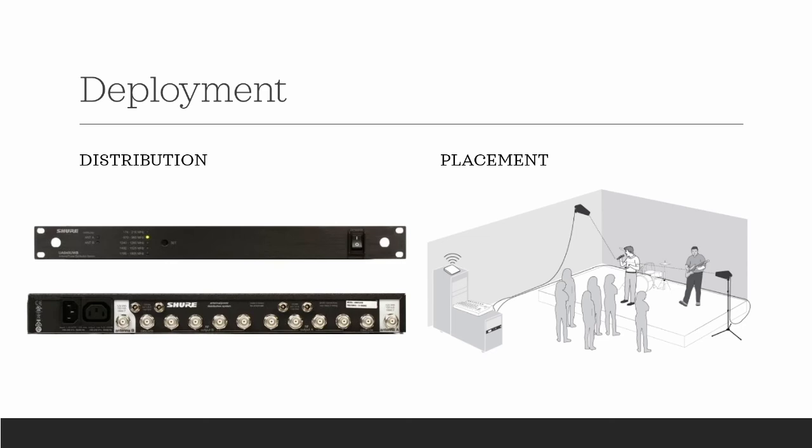And so, as I mentioned earlier, we were talking about line of sight, chain link fence, for example, is not something that would allow RF to pass through. The reason being is the metal wire creates what's called a Faraday cage, which rejects the RF. It doesn't allow it to pass. A good example of this would be the glass door on your microwave. You've got a metal mesh over the top of it, which allows light to pass through so you can see your food cooking, but doesn't allow the microwaves to pass through and cook you or everything else in the room. So that's something that we want to keep in mind as well.